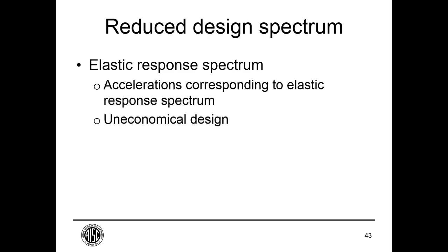It may be a perfectly reasonable approach for a nuclear power facility to not accept seismic damage. But it's not a very economical solution for designing every single house in the U.S. not to have any damage under seismic loads. Using our money to make houses that way will not keep more people housed. Instead, we allow for some inelastic response.